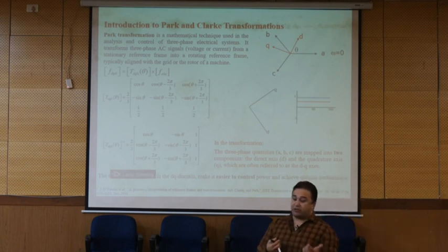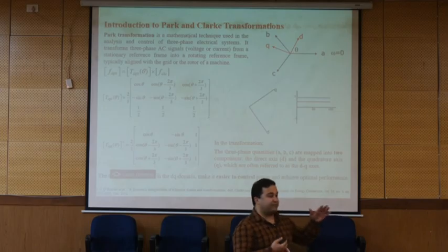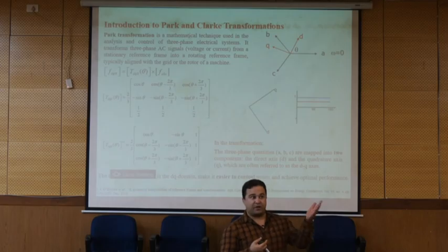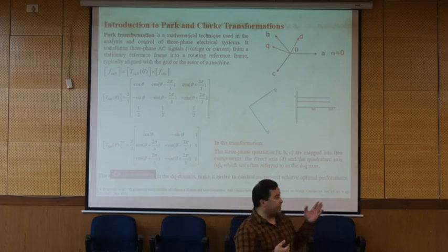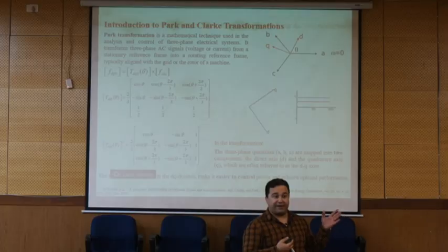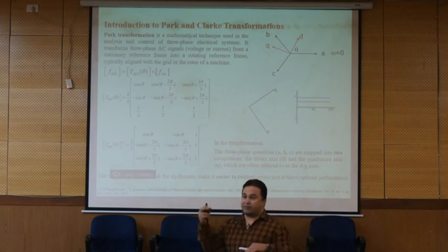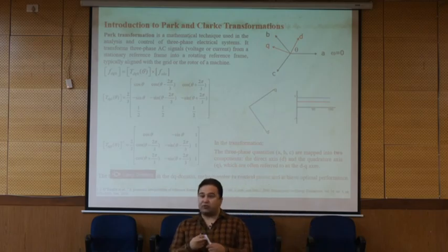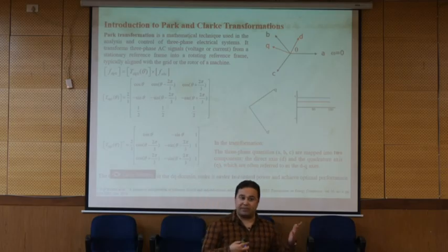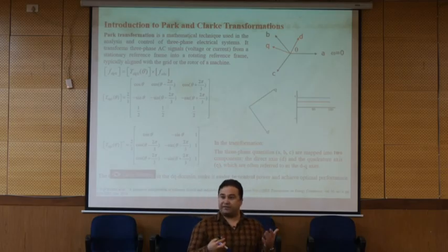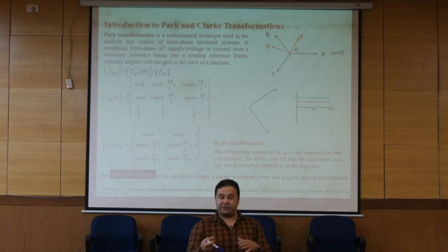And there is another option. So the first option was the active power filtering. So we call it active power filter. It means that we compensate the harmonic. This one is the power factor correction. So if you have extra power, you can merge all of them. You say that I'm going to compensate the harmonic, reactive power, and if we have extra power, then we can also provide some part of active power at the fundamental frequency.